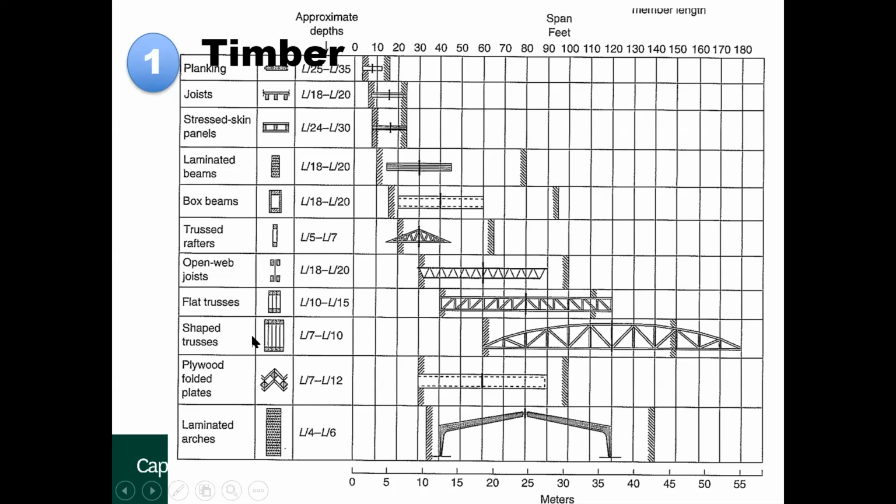Let's look at a truss. Say we've got a bowstring truss like this. Well, normally, from practice, a truss like this would start to be used for any spans greater than about 18 meters. It doesn't make sense to use such a truss for lesser spans.